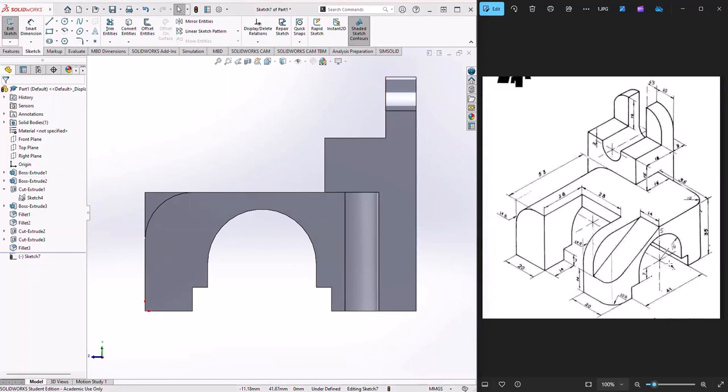You need to note that this vertical reference or center line represents the center of the semicircle that we used in the previous profile here. And if you notice again here, the start point of our line of sketch is on that center line. Okay, so this is something to note. And where does it end? We are not given an angle, but we are given another height from below. So if you look down here along that line, this line sits 14 millimeters above the bottom of the part.